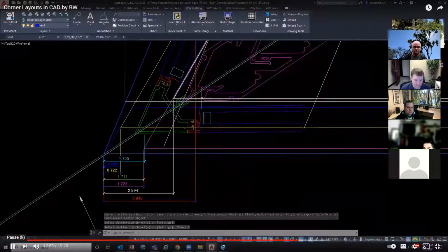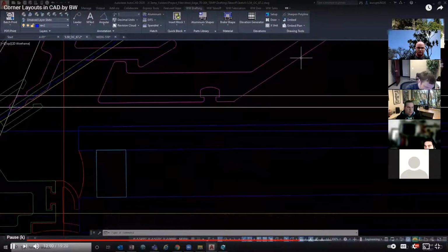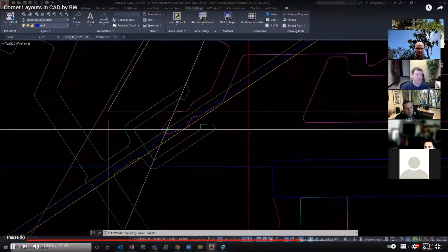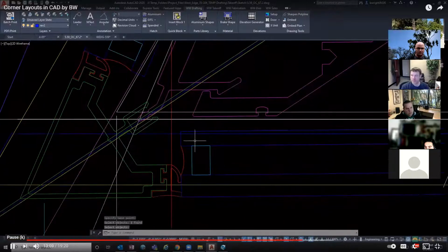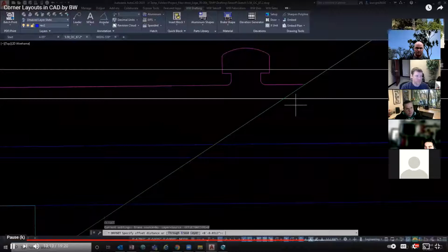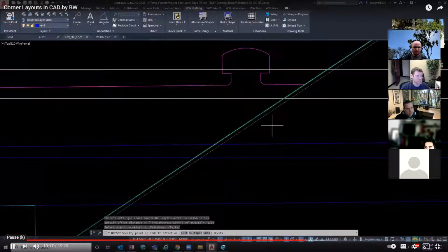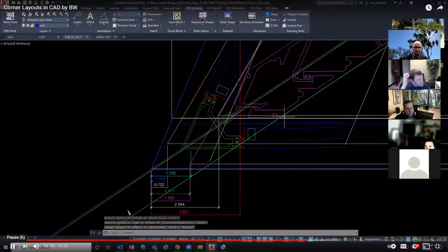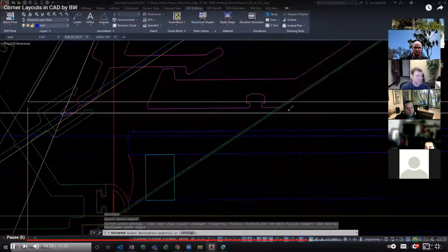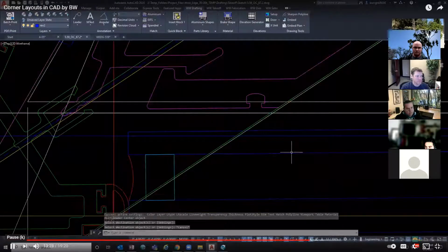Now I want to copy the center line so that I can align to the edge of this vertical. So I'll just do a copy and paste that in. I'll do an offset of 1/64. And then this one I want to match the properties and turn it white, the same color as my head stop.